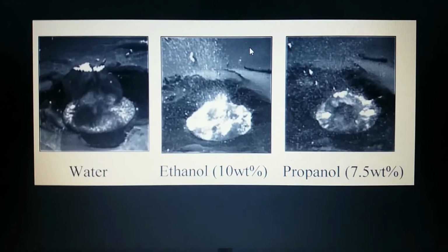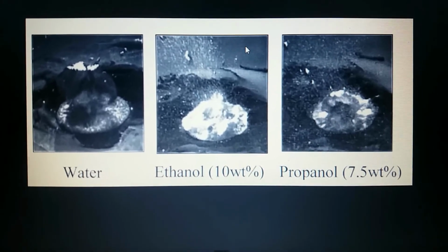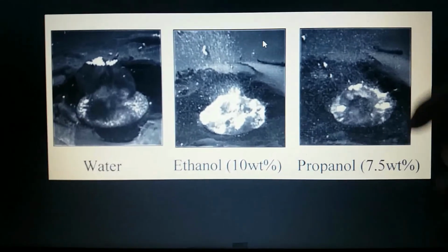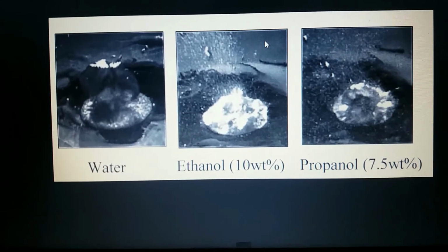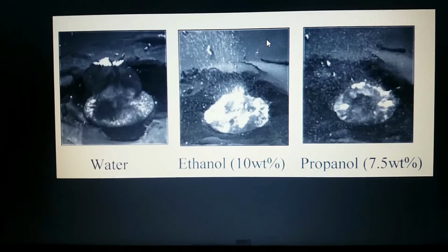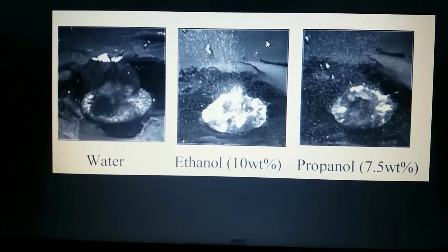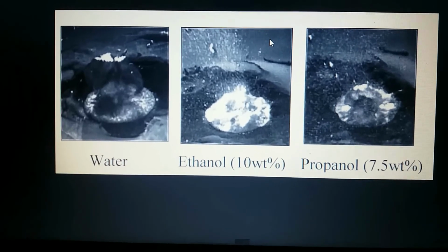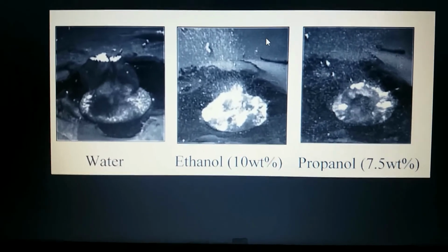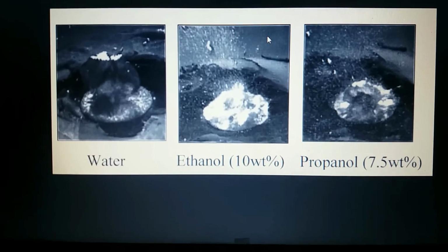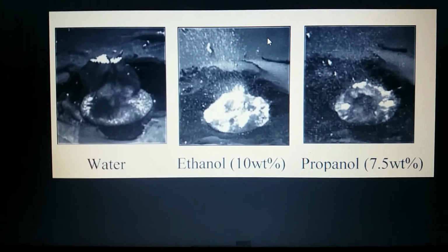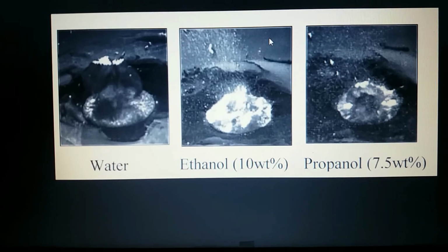Bubble behaviors in subcooled pool boiling are shown here as a typical example. A copper heating surface 10 mm in diameter is placed facing upwards on the bottom of the boiling vessel. The surface is polished with 500 sandpaper.